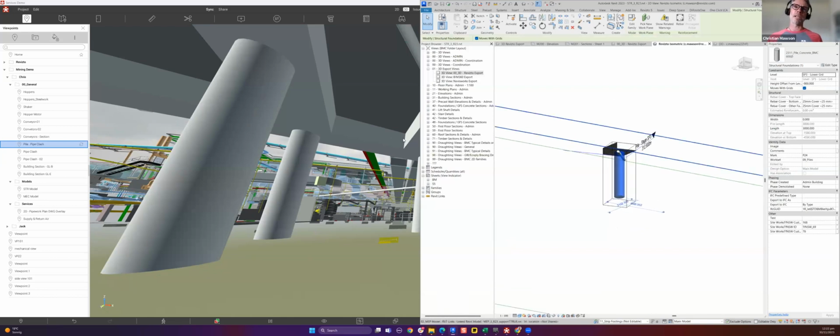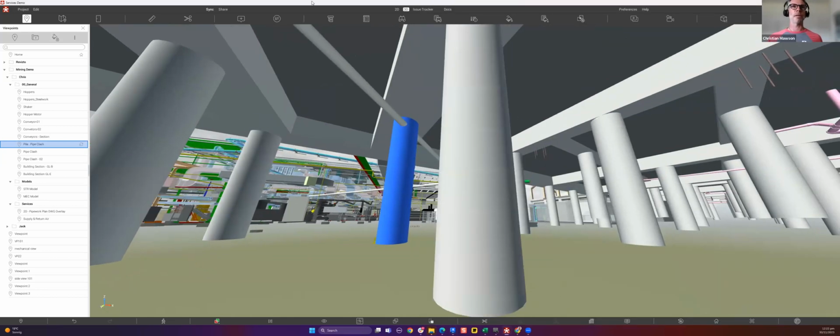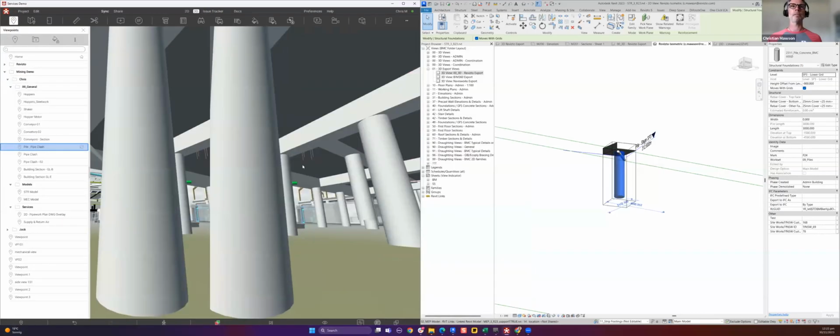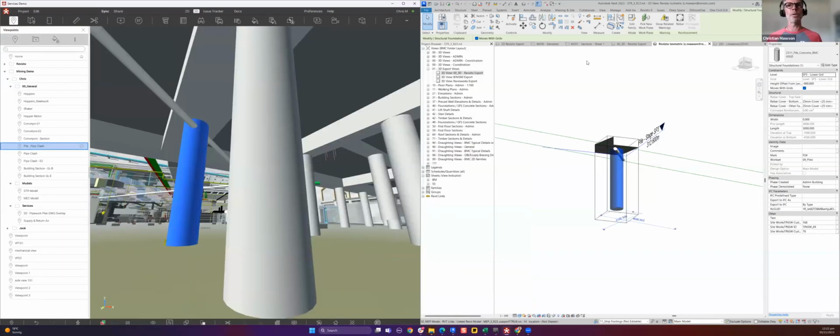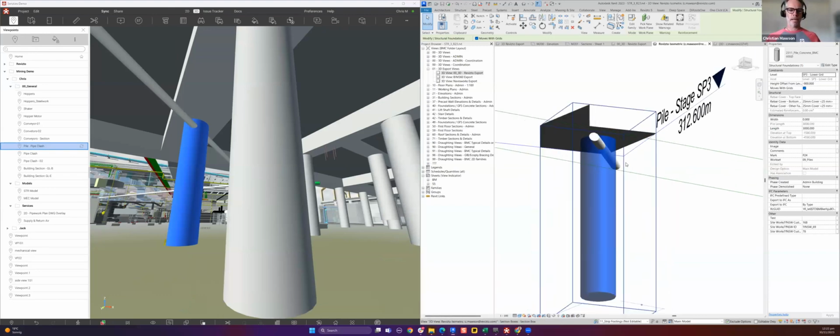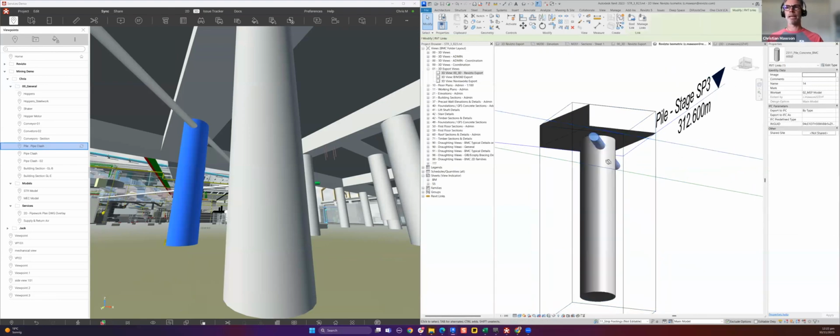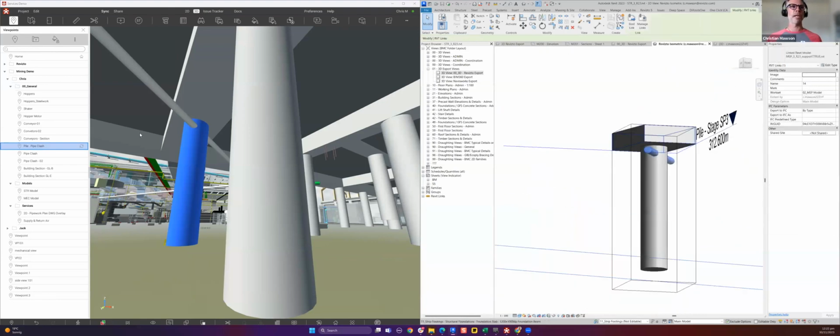And as long as I select one of the elements, or this element here, and drag it over there, it will open up the Revit model and create a box around that element. So I can now come in and actually move that drain out of the way. Super powerful tool. I can raise an issue inside of Revit, and it will push through to the issue tracker in Revizto. So it's that bi-directional link.